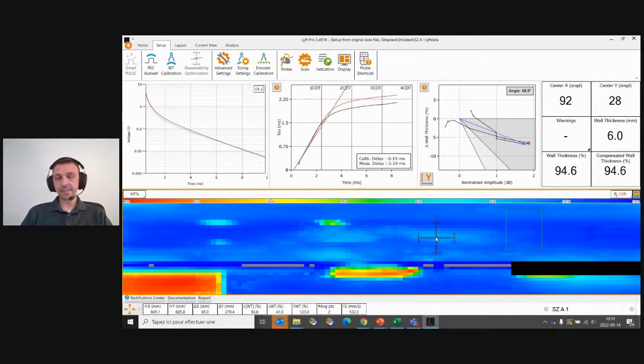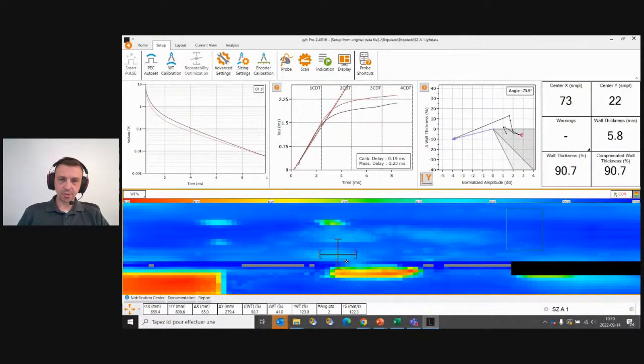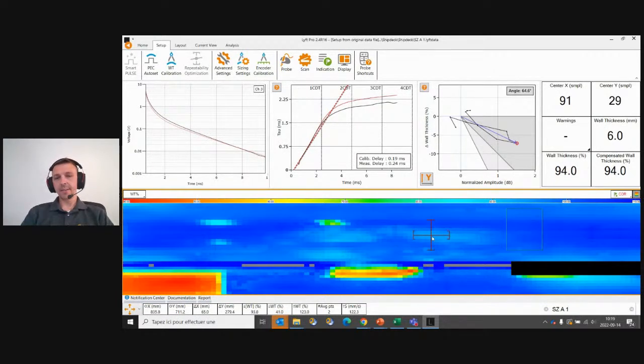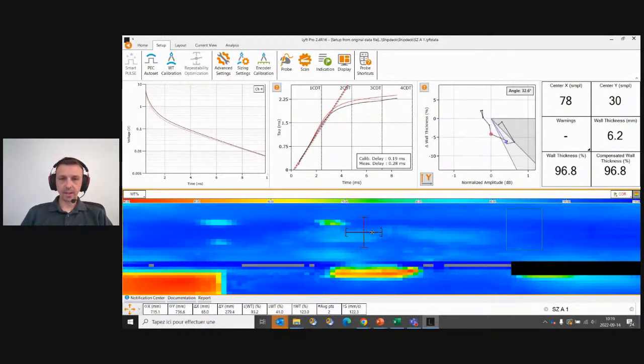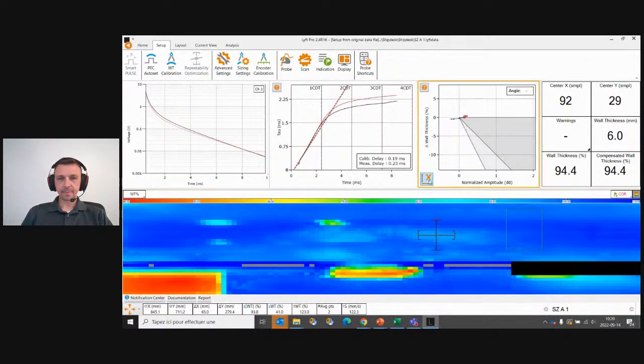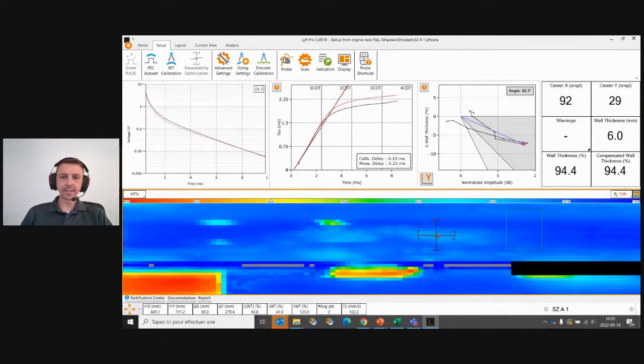So here the context is very important. This is a manufactured demo plate, which means that it was manipulated in the shop. If we look at the shape of this feature, it's like a cylinder, and this is really typical of the use of an electromagnet on a plate. So this is what we are seeing there: the residual magnetization coming from the electromagnet. We must keep that in mind when we assess the defects.